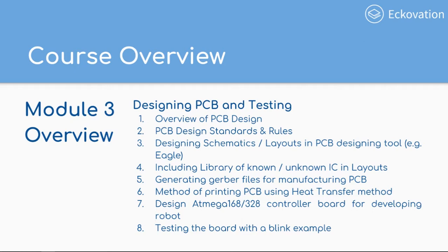Later on we will also be using the Eagle PCB designing software, and most probably the trial version of Eagle would be sufficient to build the small PCB. We will also go through the details of how to build a PCB Gerber file, because if you are interested in building a professional grade PCB, then you need to provide the Gerber files to the PCB manufacturer.